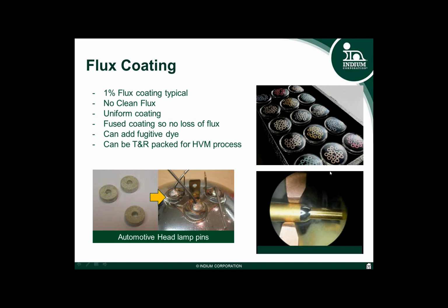Another opportunity you're seeing is a washer, and there are two doughnut washers here that have been flux coated. This is a microscopic view of a fiber optic ferrule coming from the right hand side that's being reflowed by hot air. You can see here the difference in the outer circumference of the ferrule and the interior socket.